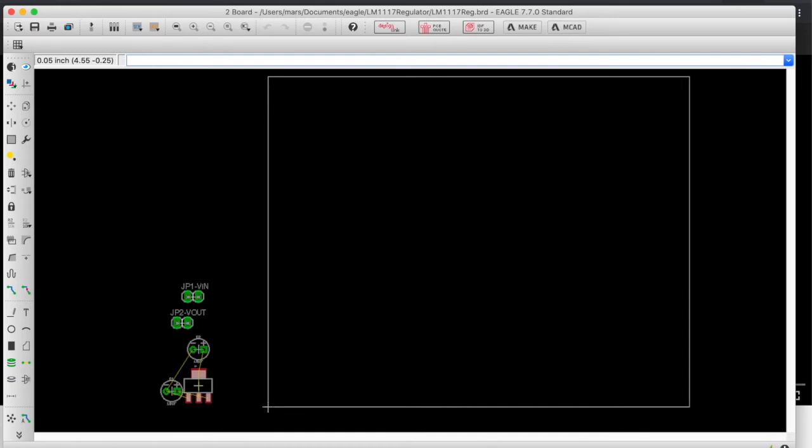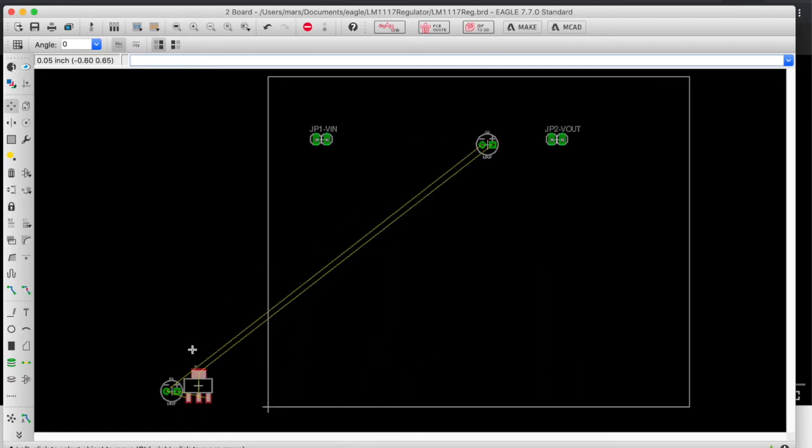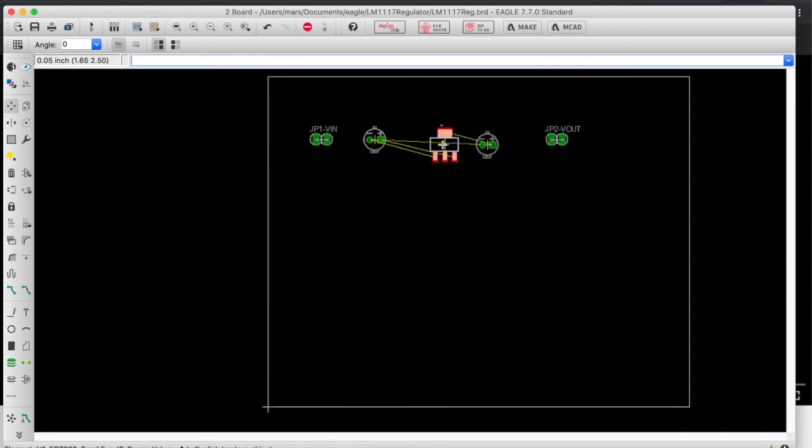All right, so as you can see, our components are right down there, and what we need to do is bring these guys into this rectangle over here, which is going to be our board. Okay, so let's just drag these guys over. We got the move tool, so we basically place them wherever we want them to end up in the finalized board, and we can still move them around once they're connected, so that's not an issue. So we need a cap at the V out terminal and one near the V in terminal, and finally the LM1117.